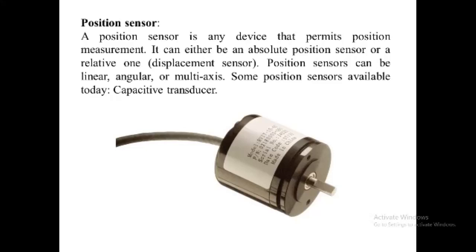For high precision, low noise applications, conductive plastic resistance element type, polymer film or cermet type potentiometers are now available. These pots have a smooth, low friction, electrically linear resistive track giving them low noise, long life and excellent resolution, and are available as both multi-turn and single-turn devices. Typical applications for such high accuracy position sensors are in computer game joysticks, steering wheels, and industrial and robot applications.